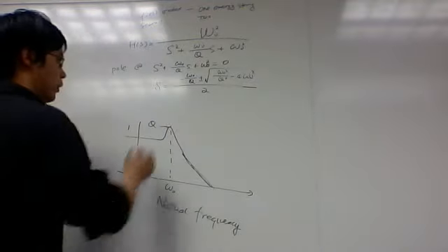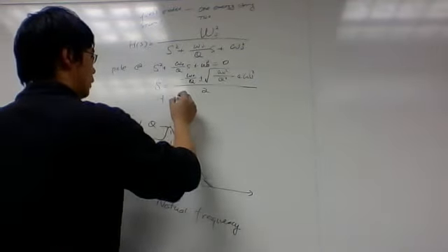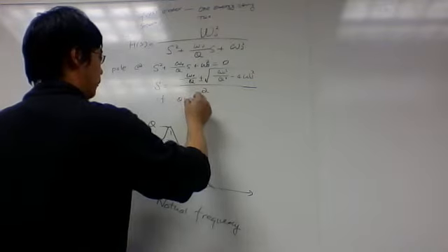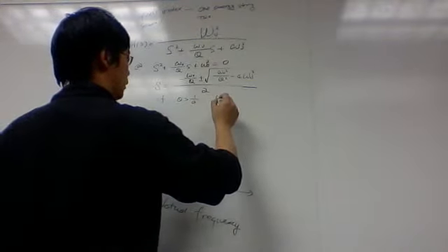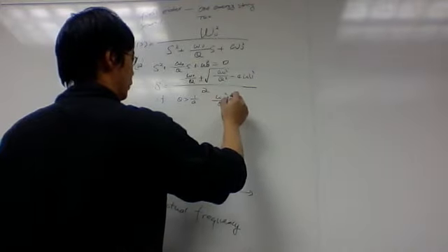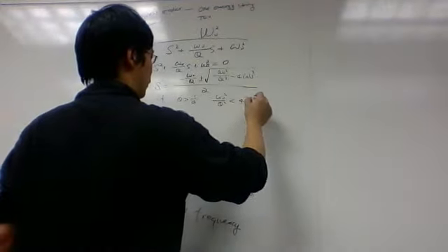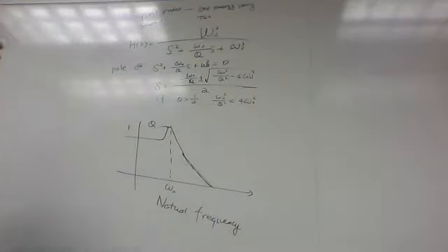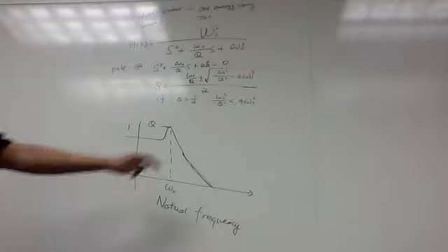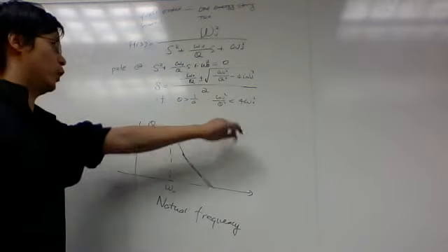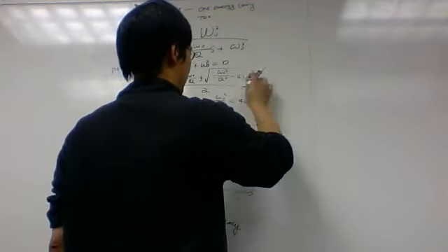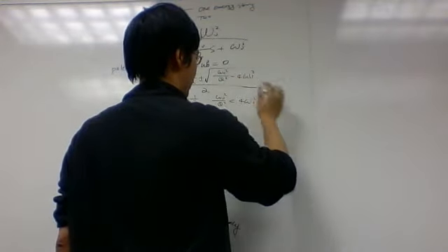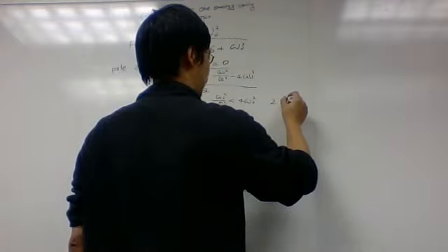Yeah. So if Q is bigger than half, right? So omega 0 over Q squared will be less than 4 omega 0, right? If the denominator is bigger, then it becomes smaller, right? So this one has to be a complex number, right? So you have two complex poles.